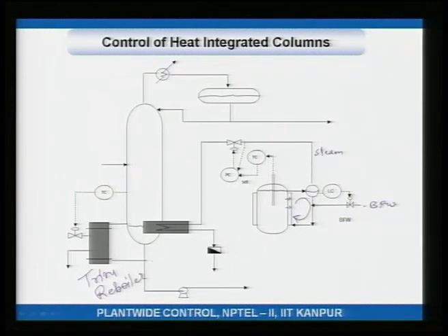Now, notice depending on what is going on in the reactor, this steam flow rate will fluctuate. So, this steam flow rate is going all over the place, it is fluctuating. Because this is fluctuating, the heat that is transferred from the steam from the reactor will vary, and therefore, the boil up here will vary. Okay. So, now let us say what I am doing is I am controlling a tray temperature by adjusting the reboiler duty of the trim reboiler.